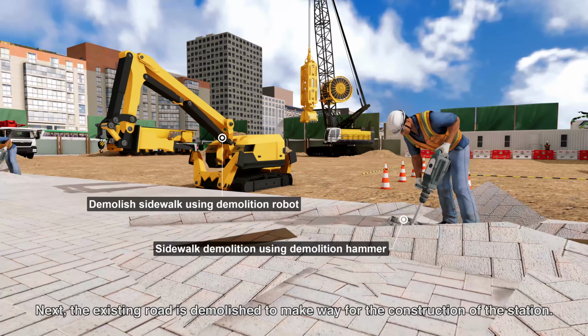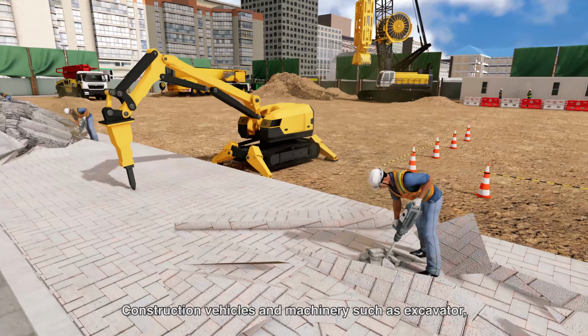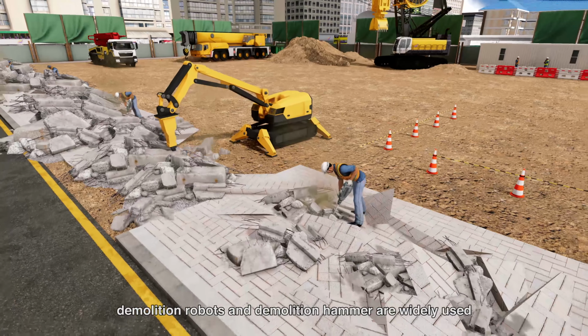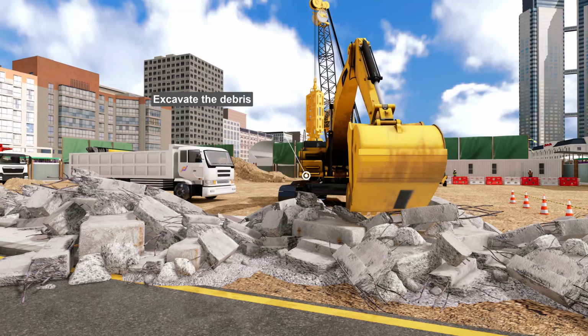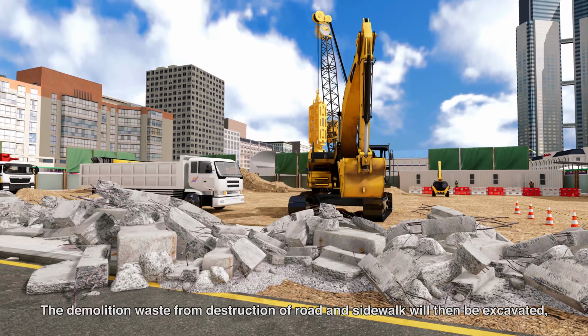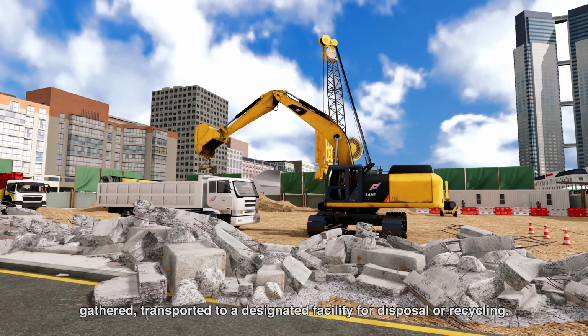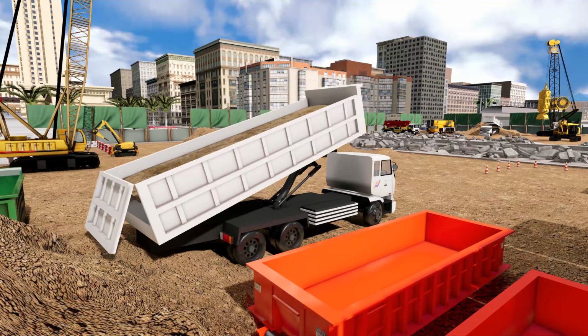Next, the existing road is demolished to make way for the construction of the station. Construction vehicles and machinery such as excavators, demolition robots and demolition hammers are widely used for the road demolishment and excavation. The demolition waste from destruction of road and sidewalk will then be excavated, gathered and transported to a designated facility for disposal or recycling.